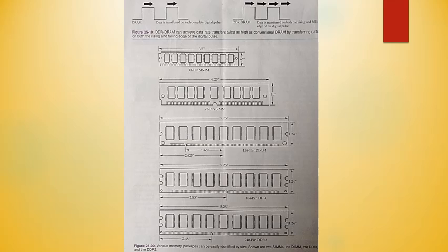DDR2 is the next generation of DDR memory. DDR2 operates at a lower voltage than DDR. The lower voltage counters the heat effect of the higher bandwidth produced by the module. DDR2 uses a different motherboard socket from DDR and is not compatible with motherboards designed for DDR. The DDR2 DIMM key does not align with the DDR DIMM key. If the DDR2 is forced into the DDR socket, it will damage the socket and the memory will be exposed to high voltage level.